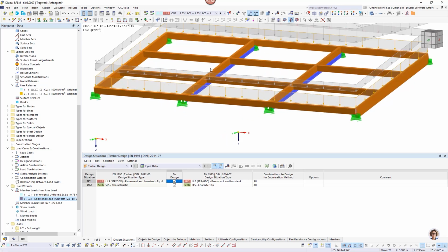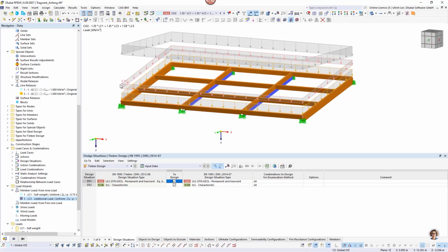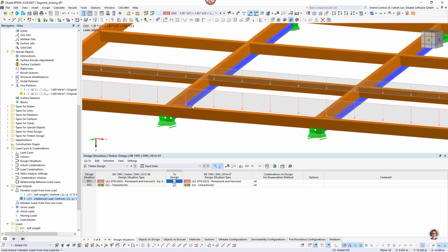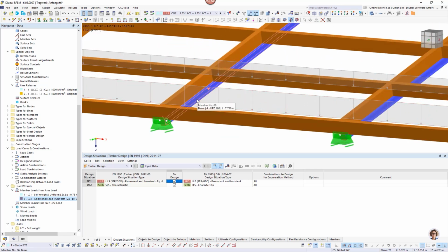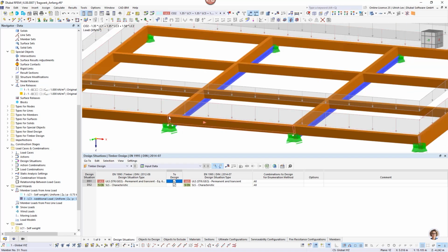But my main beams have a deflection, have stresses from the self-weight before, and after that I screw these new steel beams with the main beam, and these main beams have to get additional deformations before these steel members can be acting.